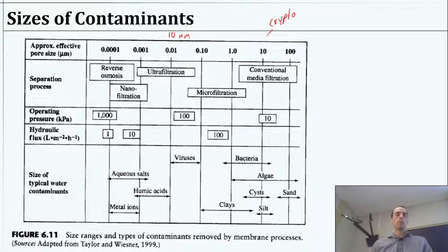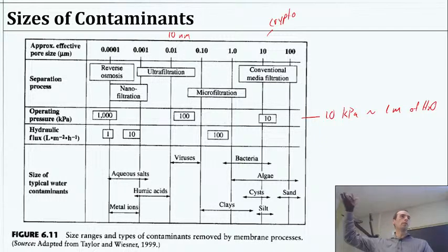So there's a bit of a sweet spot. And the pressure, by the way, for every 10 kilopascals is about 1 meter of water, of hydraulic head, meaning like 1 meter above that spot. If you have a meter stacked up, that's 10 kilopascals of pressure.